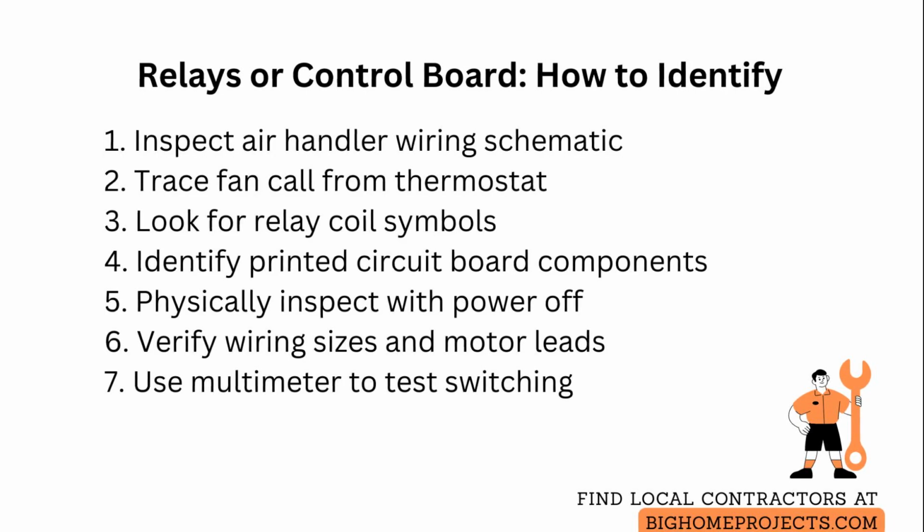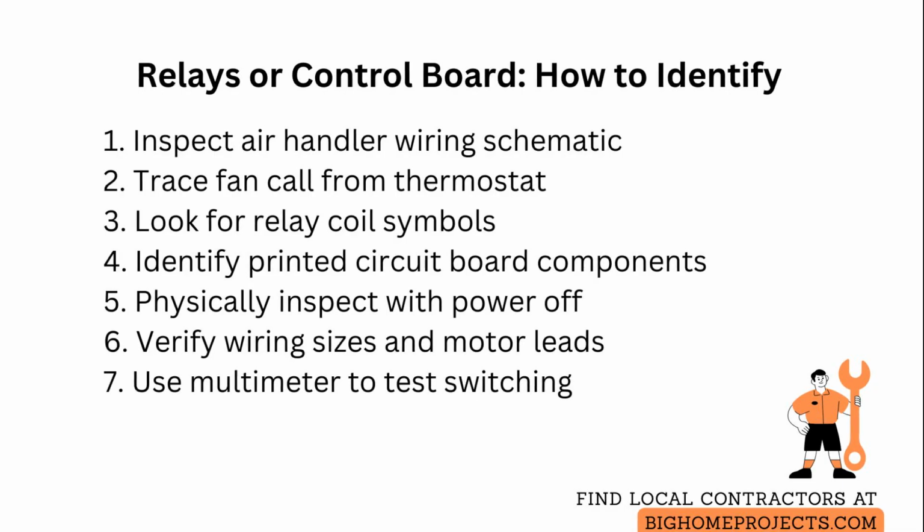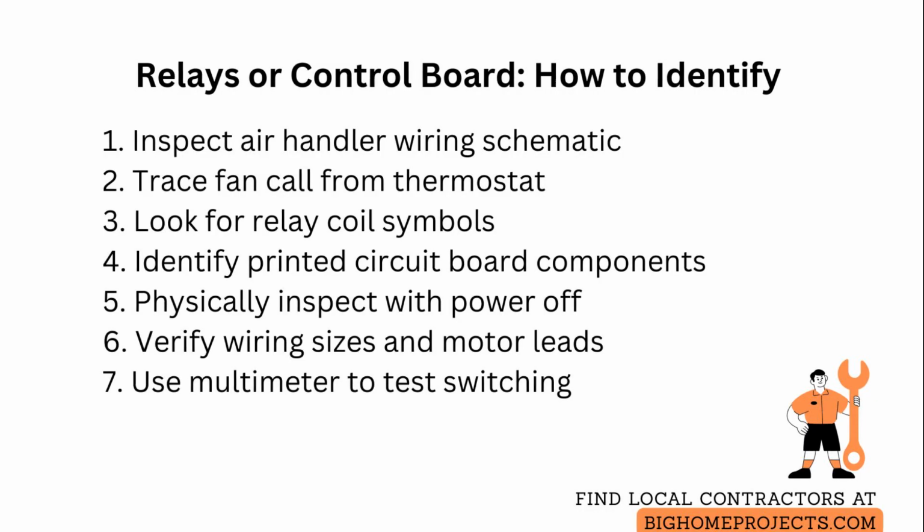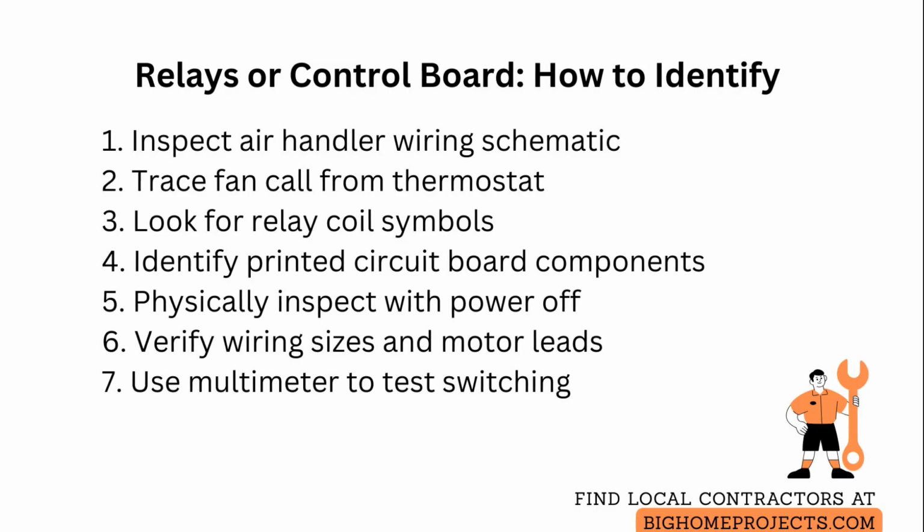While you are there, confirm line and load wiring sizes and that the blower motor leads are going to the device you identified. Use a multimeter on the low voltage terminals to verify whether the fan call energizes a coil or simply sends a logic voltage to the board.